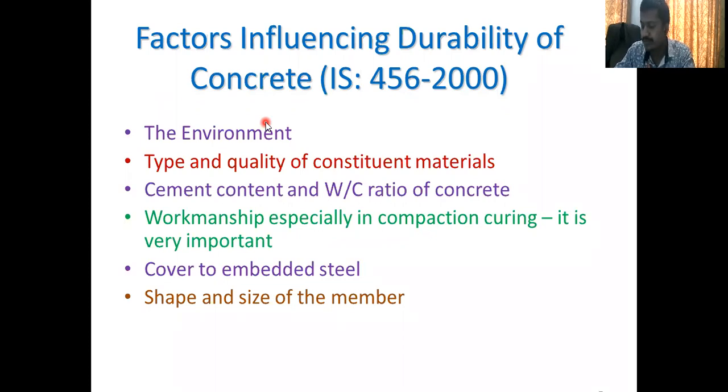As I told you, M20 grade of concrete, suppose just take one example. I think I have discussed this example with you. For M20 grade of concrete, if you carry out the rate analysis for 1 meter cube, you require around 6.5 bags. Okay, around 7 bags. Okay. So, and you have done the mix design.